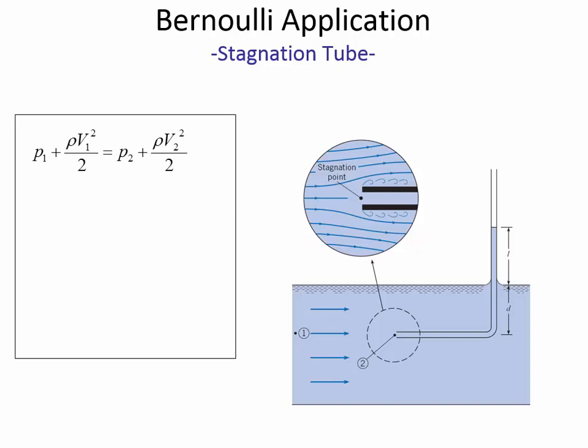So that's Bernoulli's equation. And what we're saying with the stagnation tube is all of the energy that there was at 1 is also present at location 2. It's just that it's changing form. There was some velocity head at 1 because the flow is moving, but just at the mouth of the stagnation point, there isn't velocity anymore. And so the energy that was tied up as velocity is being transformed into additional pressure. And so we can use that idea with the stagnation tube.